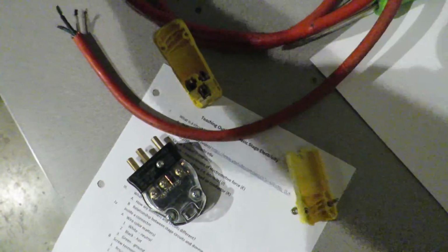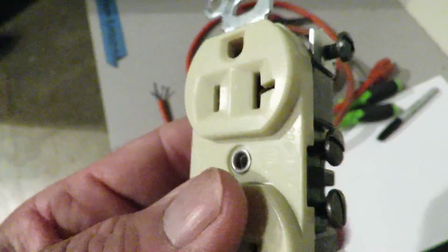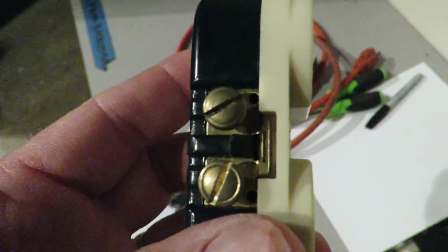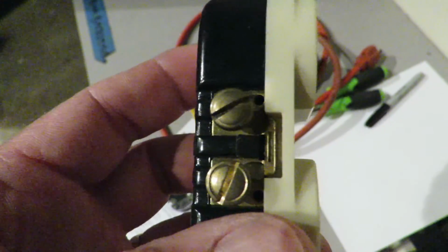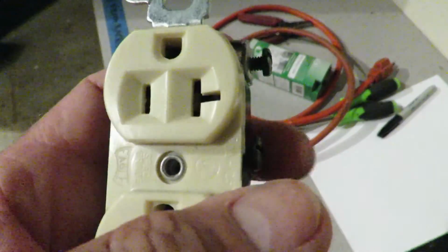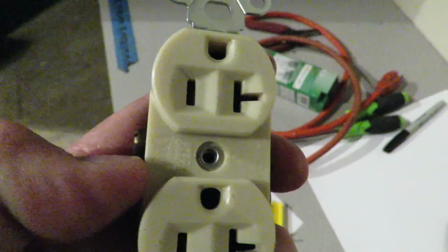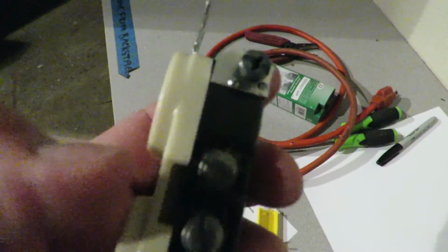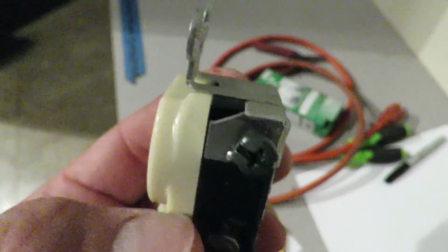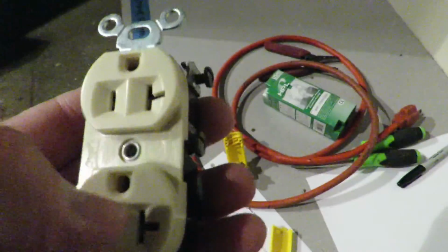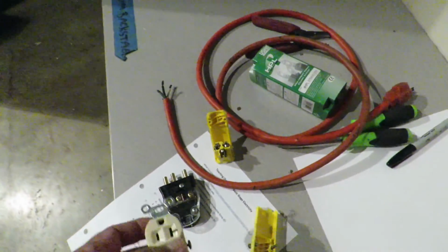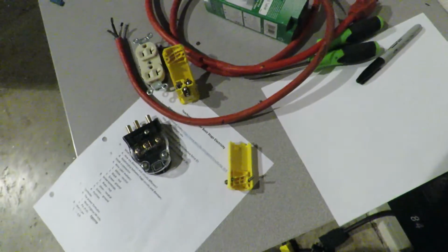pin on the connector. The exact same thing would be true if you were looking at a wall receptacle. Notice there's black or brass screws for the hot wire. There are silver screws for the white wire. And again, you can tell goes to the biggest blade and the smallest blade for the black. And then that leaves this ground pin. It's green, it's supposed to be green in color there all by itself, which goes to the ground pin. And the same thing would be true for a light switch or anything else.